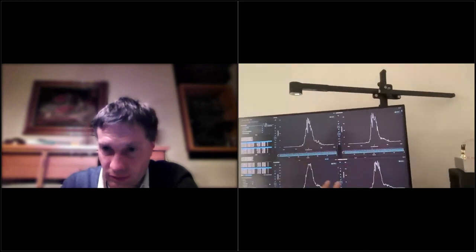You can see some minor effects, but overall it doesn't make that much difference when the refresh time is high, because there's not that much holdover to really see a significant difference between a TCXO or an XO. But as you make the refresh time much lower, for example 0.2 hertz, every 5 seconds, then you start really seeing things, and you see that the tail basically started to increase. It's very interesting. So, back to you.